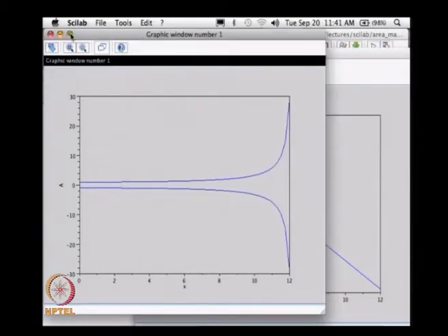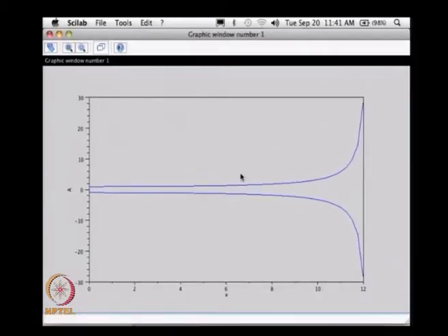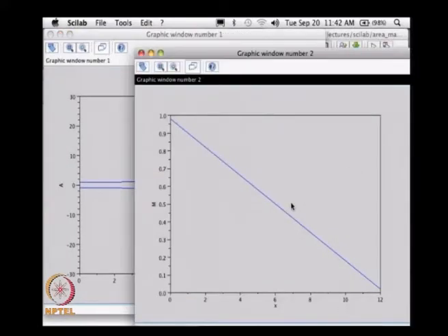Let us look at the corresponding change in the area. What you see over here is that the flow is subsonic in the entire region. As you increase the area, and the area increase is quite gradual, the velocity is decreasing, because the Mach number is decreasing.